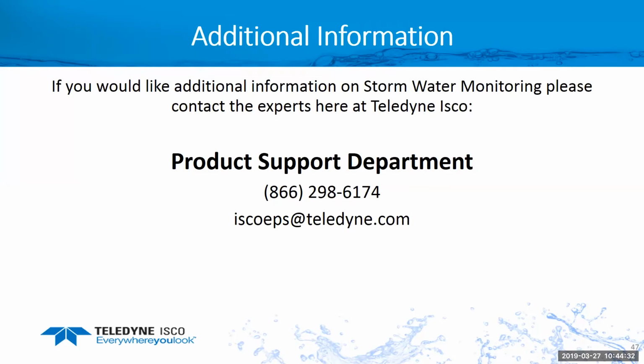Okay. The next question is about the laser. They're basically saying the laser uses the speed of light. How do you control the distances to measure specific depths? Okay, so what we do here is the ultrasonic is actually playing multiple roles. The ultrasonic sensor measures the depth of the water to calculate our area, so we know the pipe size and shape, and we know how much water is filled up in there. What that ultrasonic tells us is not only the level of water in the pipe for area calculation purposes, it's also used to let the laser know where to focus its beam.